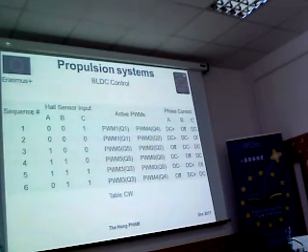So the current will flow from A to C. And in the second stage, it will flow from A to B, right? And at the third cycle, it will flow from coil C to coil B. And this sequence will repeat in order to work as a stepper, right?